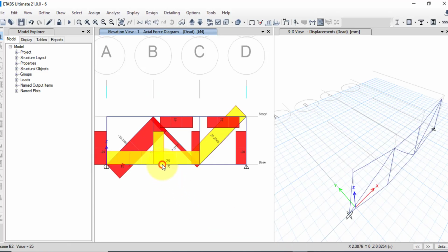At the end, I would suggest you remember the assumption that in a truss all joints are pin connected, and in a truss we have only axial forces, no shear force or bending moments. Actually there is movement, but it is a negligible value, so we can neglect it.